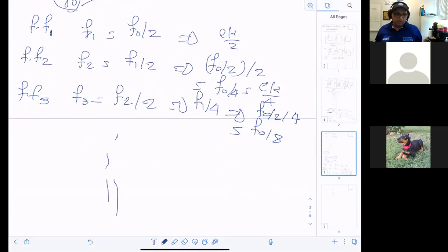Yep, makes sense. That's why I didn't want to put too much on it, because it's still counting, right? You just need to know the difference. The only difference is that in synchronous counters all of them share the same clock. For the asynchronous, every single output is a clock for the consecutive following flip-flop, and you move forward. What you are doing is dividing by 2, and if you look at it, it's accumulated. So it's going to be 2 power 1, 2 power 2, 2 power 3, 2 power 4, and so on.